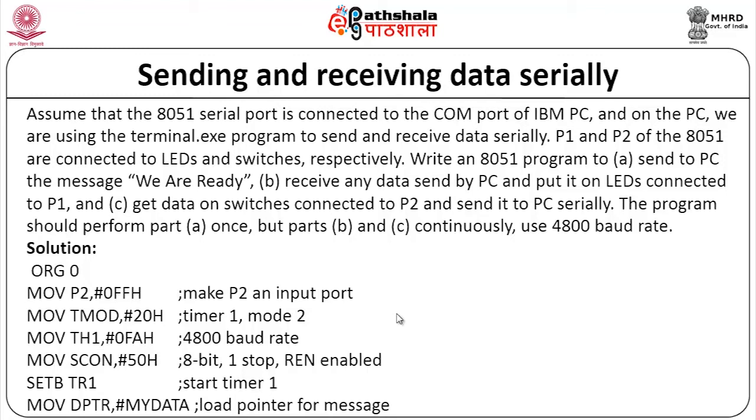The program should perform the message sending only one time, whatever data we want to send from the PC. Once that is done, the communication between the LEDs and the switches is done continuously, and all of this has to be done with a 4800 baud rate. This is what we have demonstrated with this particular program.